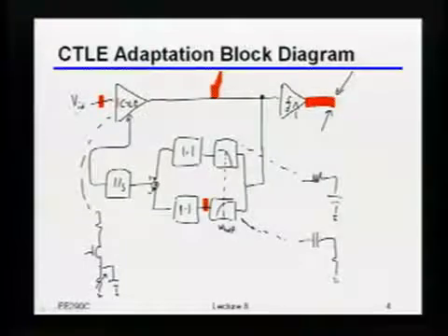And then if they really have a fairly complicated channel, they'll deal with it either with the transmit pre-emphasis or with the DFE or both. And for those, I'm about to show you exactly how you can adapt to basically arbitrary channels. So that's a great question. Other questions on this?